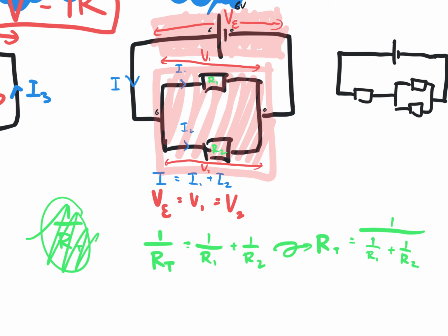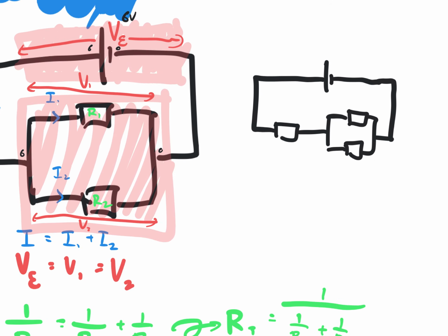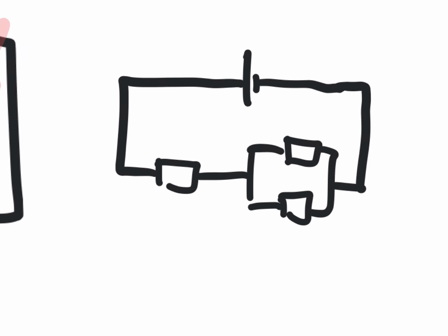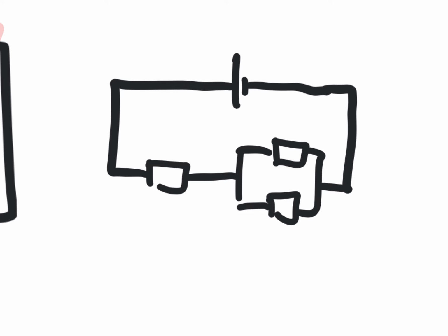Okay, that's 10 minutes. Now let's go on to try to solve and work out some of the questions which look very similar to this. Okay, now what is the method for solving these types of complex circuits or composite circuits? Well, here are the rules, or what are the methods? Number 1, you're going to try to simplify things as far as possible and make everything look like one big resistor, so to speak, right?